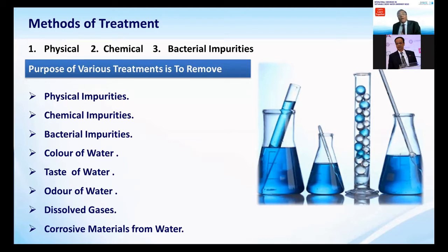That required quality is given to you by your machine supplier or the process developer. Like in textile, you will have to see for the dyeing, finishing, and bleaching what type of water is required. Normally, high pressure boilers having 80 bar pressure require conductivity less than 0.01 microsiemens per centimeter.